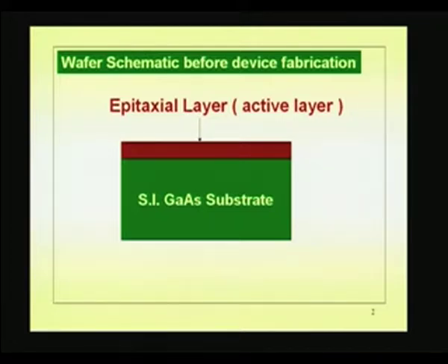When you grow the crystal, when you grow this layer, that is the epitaxial layer, the meaning is you are arranging atoms. You are arranging the atoms of gallium arsenide on the semi-insulating gallium arsenide substrate. And if you give proper opportunity to these atoms which are being laid out on the surface, they will take the same crystal structure as the substrate. So, that is why you can call it autoepitaxy or homoepitaxy. If the substrate is doped differently, it is still called homoepitaxy. N-type, P-type does not matter.